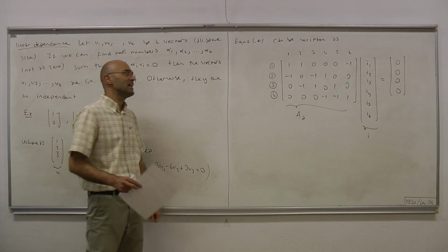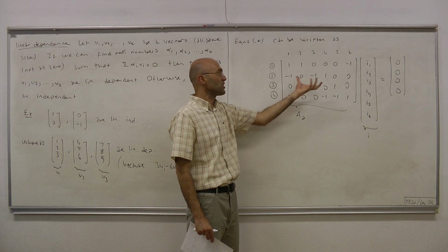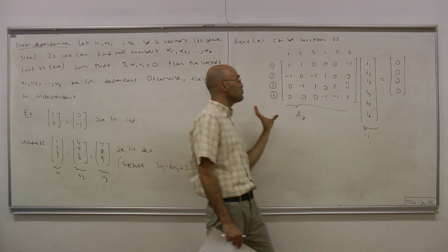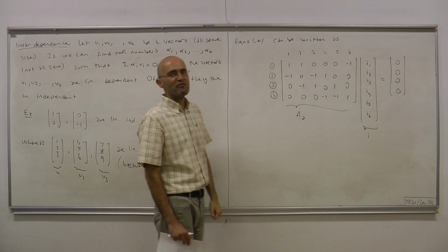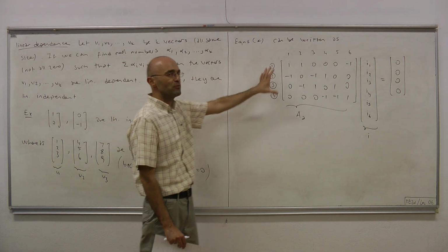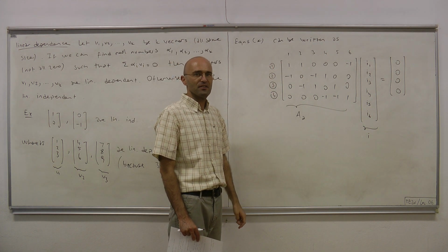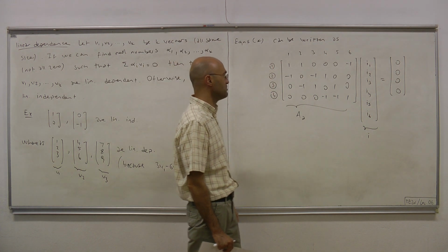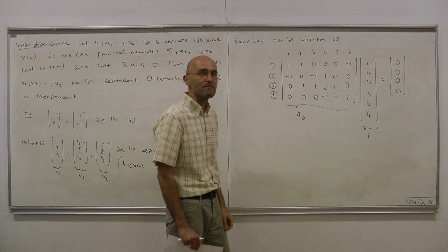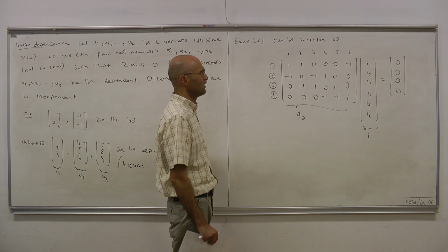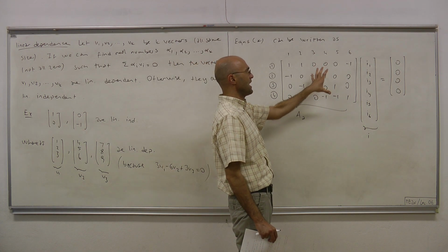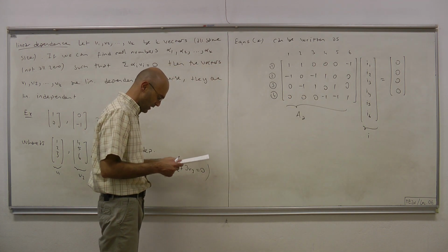And when we have linearly dependent rows in such an equation, the individual equations coming from that matrix must be redundant, superfluous, meaning that there's a more economic way to express KCL in this case.